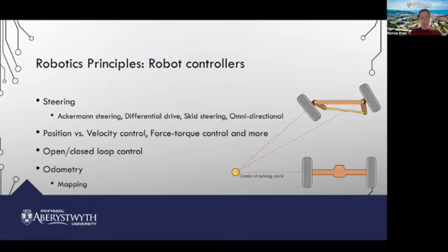So the first of these, perhaps of the larger scale robots, is what we call Ackermann steering. And this is where we have two front wheels connected together by a sophisticated axle. And actually the way we often compare these steering mechanisms is by looking at where the center of turning circle is for that particular configuration. And in this case, where we have a four-wheel vehicle, then the center of turning circle is aligned with the rear axle, and the angle of the front two wheels is coupled together and controlled by a single steering angle to maintain that center of turning circle angle.